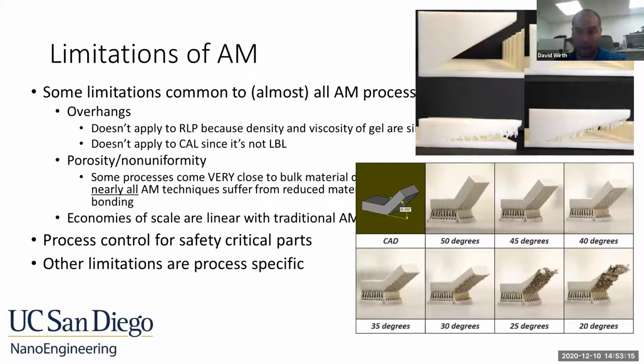And even to an extent, composites, we're starting to understand how they fail and how they perform. But with 3D printed parts, it's kind of a question mark. It's kind of a mystery. We don't fully understand how they fail, or it's not a mature enough process. And so people are kind of wary of putting 3D printed parts into safety critical applications because we don't fully understand how they fail and the kind of defects that can form.